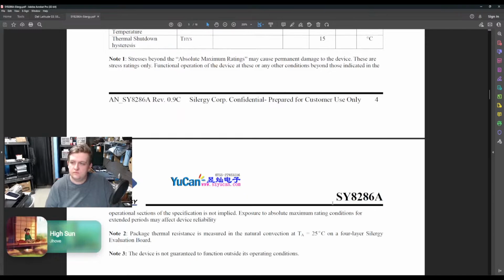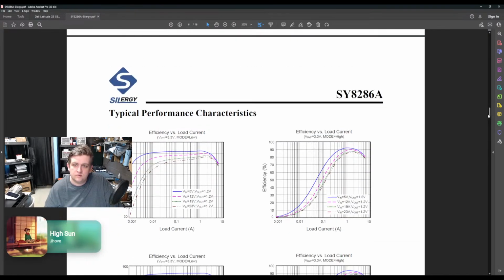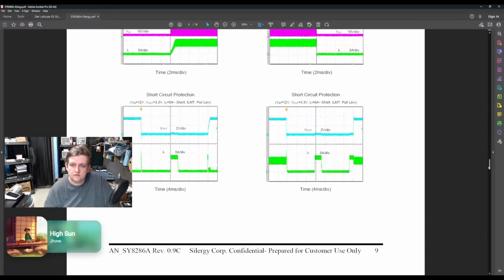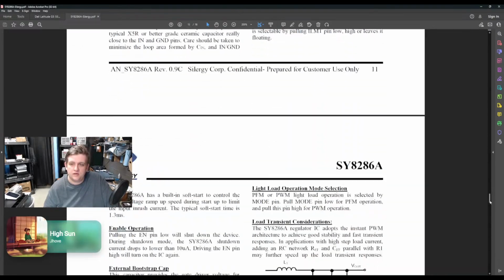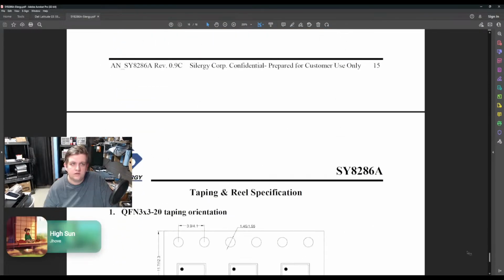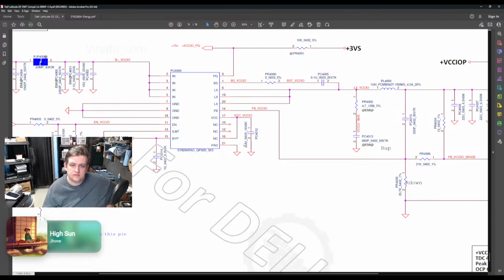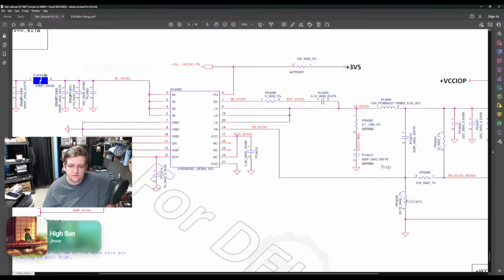Okay, I love diagnosing and trying to figure out, especially when I find a blown component, what happened. Something shorted to ground, I believe, is what happened, and quite possibly it was that power supply. Maybe I can find where this chip leads off to. What was it, pin 17, an output? Pin 17 is an output. So I wonder if I plug up the power supply. Let's see. Plugging in the power supply, I might be able to get a reading off. Maybe, I don't know. I'm going to see if we can find a replacement for that chip though.